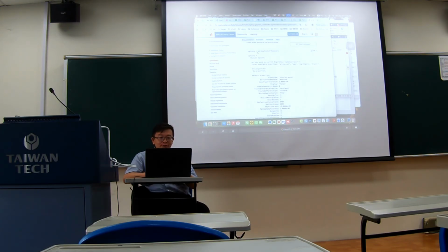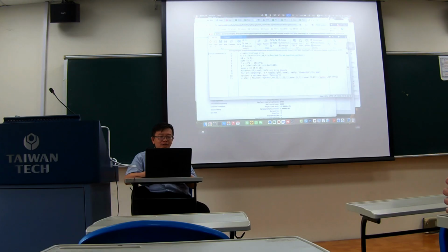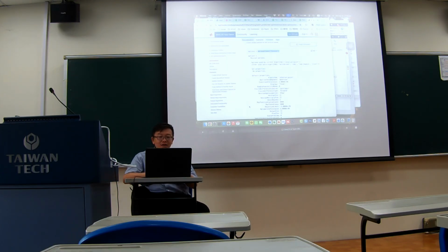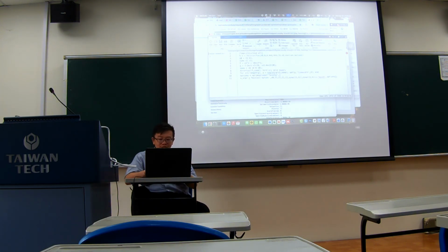So here, optimoptions. Okay, so for fmincon, what do you want to do? I would like to choose my algorithm. So algorithm, and then use SQP.